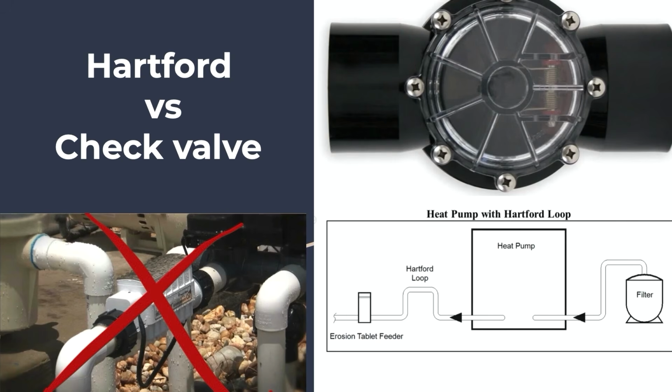And I don't have anything I need to say about the Hartford loop, other than that if you are installing a pool heater, you need some method. So build one yourself if there's not a loop or a check valve in place. So one or the other, not both necessarily. You don't necessarily need both.